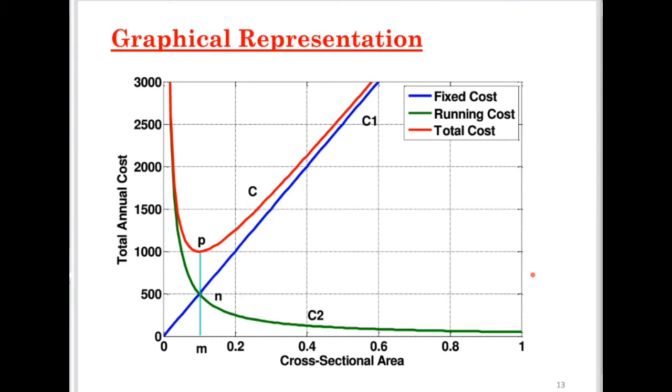Now, we saw in the beginning that when we are talking about Kelvin's economy law, it gives us the total minimum cost incurred in terms of the conductor cost and the cost of energy in the line. So it gave us that the cost of conductor should be equal to the cost of energy wasted in the conductor annually, meaning C1 should be equal to C2. And we also found that the total annual cost should be the minimum. That was the condition, and from that we found those conditions.